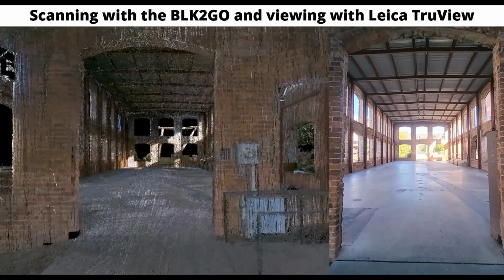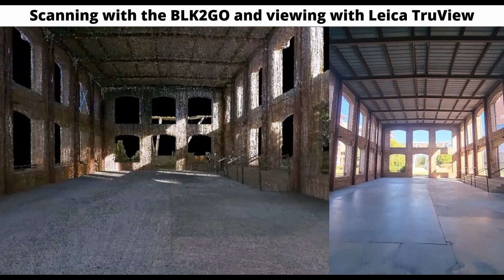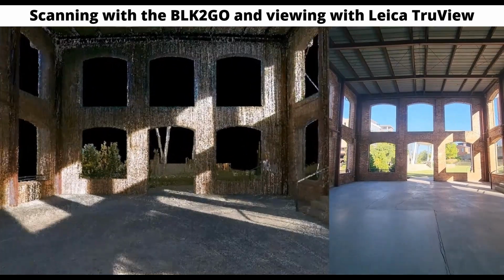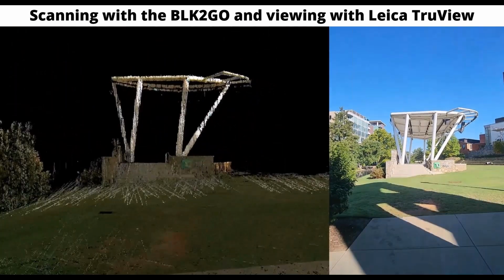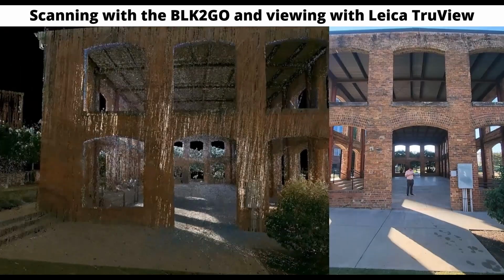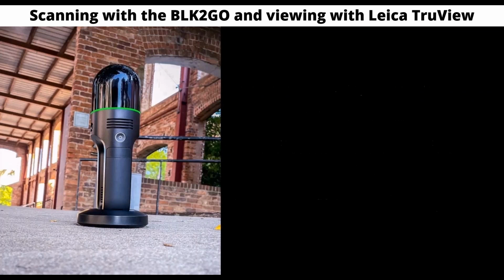And the pace that you walk at controls the density of the data that it's capturing. And as you can see right here, we're walking at a pretty good pace, but we're capturing a tremendous amount of data here. So this allows you to capture data just incredibly fast. And we found many use case scenarios for this type of scanner, as well as the more traditional scanner. Now, it uses a technology called SLAM, or simultaneous localization and mapping, so that it's looking at its surroundings and understanding its surroundings as you're walking.